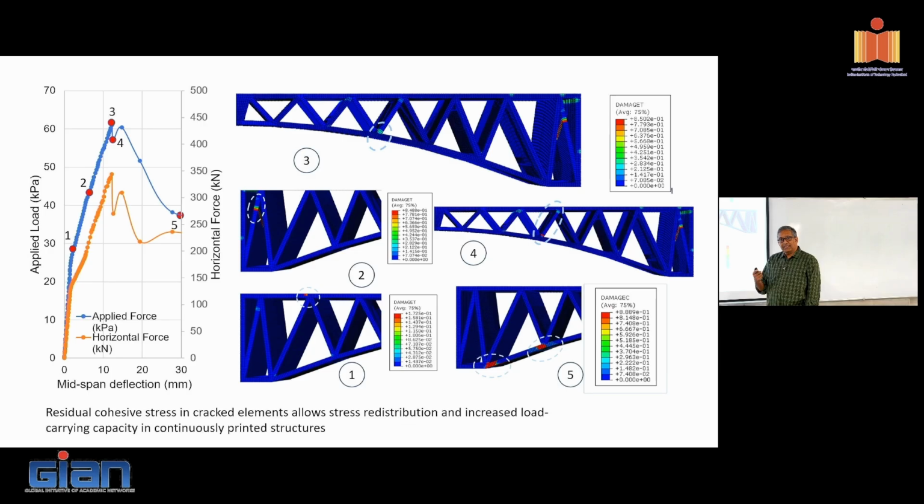Now, although the tension cracks form in the diagonal ties, because I have that little wire hanging in there, it's able to transmit a small amount of tension. What happens in the process is that this is where redundancy in the structure comes in. So when this tension tie cracks, the stress is redistributed inside the structure. Basically the other elements start picking up stress. And slowly up to 0.3, we see more and more tension ties start to crack, and there is an increasing redistribution of stress happening within the structure here. Final failure happens at 0.3, where, remember, the bottom arch is in compression.